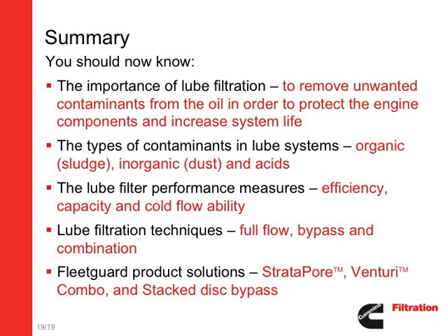Now that you've completed this section of your fleet school training, you should know the importance of lube filtration, which is to remove unwanted contaminants from the oil in order to protect the engine components and increase engine life. You should be familiar with the types of contaminants in the lube system, including organic, sludge, inorganic, dust, and acids.